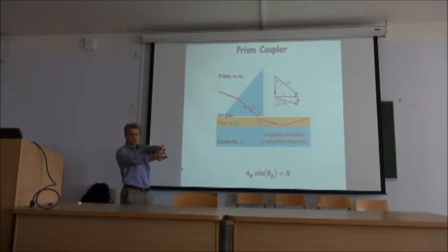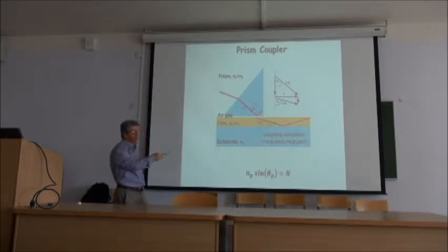As long as you have overlap, you're going to get light coming in. But you want to match that excitation, that gap, so that the rate you couple in is the one you also couple out, to minimize the loss inside the guide. So this gap here, roughly speaking, is going to be a fraction of the wavelength.